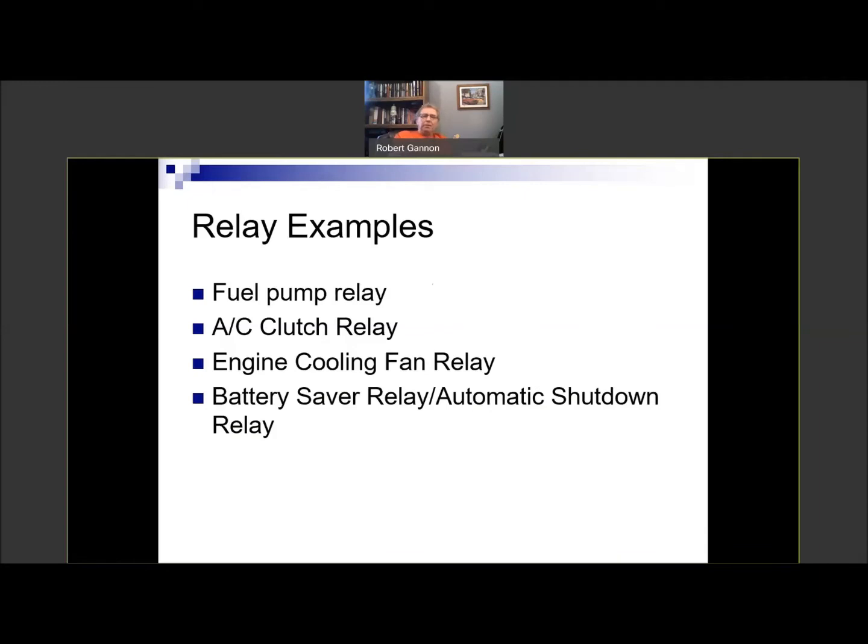Here are some examples. Fuel pump relay, AC compressor clutch relay, engine cooling fan relay, battery saver relay or ASD relay, very common nowadays. They provide power to most of the electrical system when the key's on, and then if you leave the vehicle for a while, they turn off so as not to kill the battery.